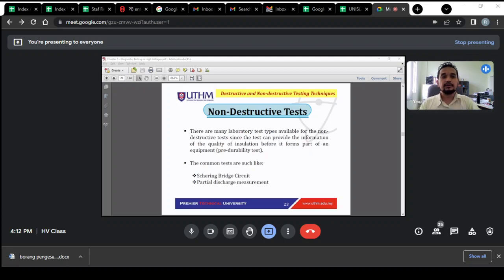Oh, no. Not necessarily. The cross arm structure earlier is just an example. You can test an insulator string. Say for example, you propose to make an insulator, and we want to test the insulator. What we do is suspend the insulator, clip the top one to be the high voltage and the bottom one to be the ground. And then, that's it. Just apply the voltage.